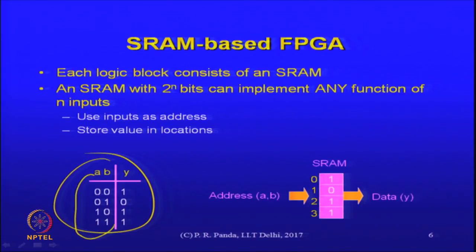All of this is already known. The left side of the truth table is all known. So what remains is that one output column. When I say any function, what do I mean in terms of realization? You just need to give me a way to realize that column. So you can see there is an application of a memory element like an SRAM. It's kind of like a lookup table. These are called lookup tables.